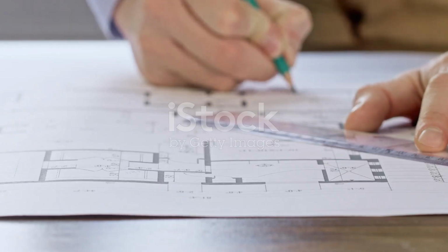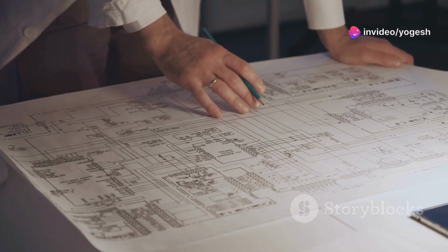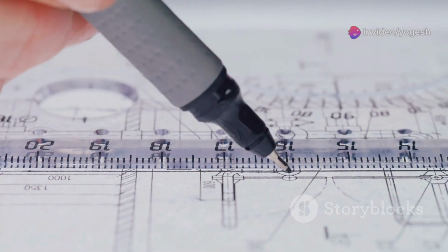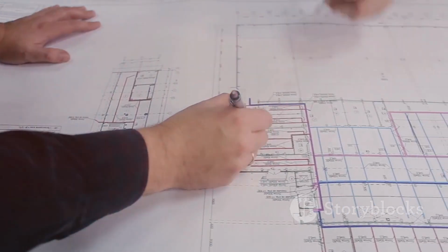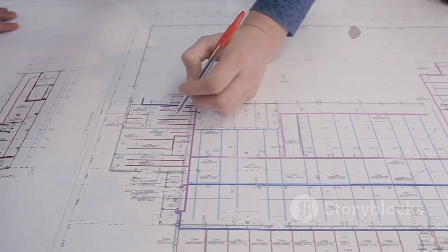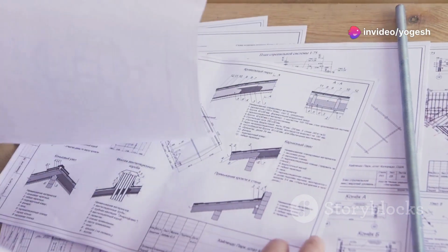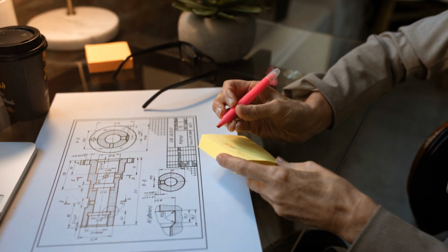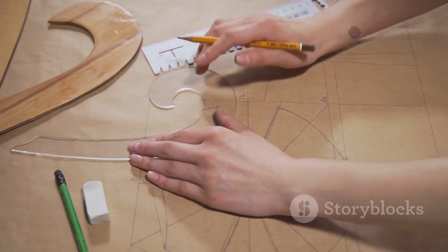Our first tip is all about being crystal clear with your dimensions. And when I say clear, I mean leaving absolutely no room for interpretation. Don't rely on someone scaling your drawing or making assumptions. Give them the exact numbers they need. Always dimension from a known datum or a clearly defined edge. This creates a consistent reference system for all your measurements. Avoid redundant or conflicting dimensions like the plague. They only create confusion. If a single dimension can convey the information, stick to that. Remember, we're aiming for clarity.